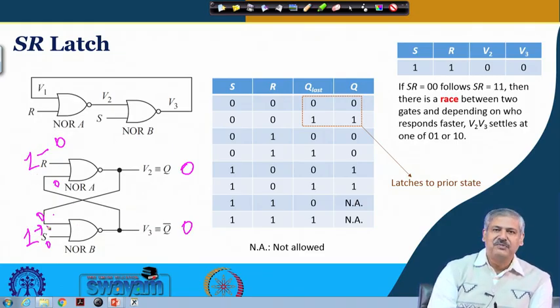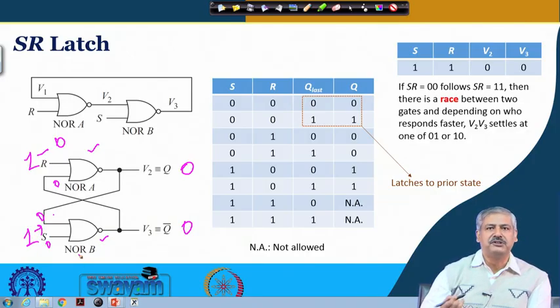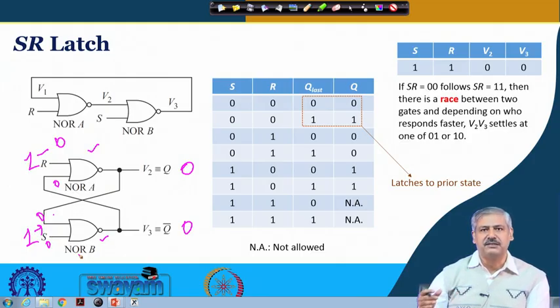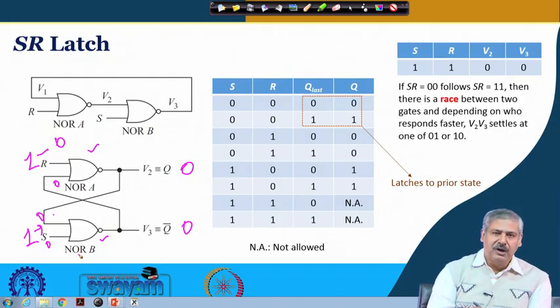Okay. So, that is the ideal case, but actually, whatever the fabrication process, the propagation delays are not identical. Because of the way the different transistors and other elements in the circuit get fabricated, one of them will have a higher propagation delay than the other.